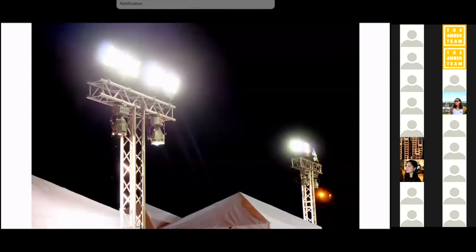Now, aside from LED and compact fluorescent and incandescent halogen, we have a class of lights called high intensity discharge, HID. And these are the ones that produce a ton of light. We use them for stadia. We use them for parking lots and roads, or at least we used to before LEDs. And they take a long time to turn on, maybe 10 or 15 minutes. And we can dim those, but dimming an HID actually requires quite a bit of equipment, and it's not the kind of thing that can just be within the equipment of the light fixture or light switch itself.